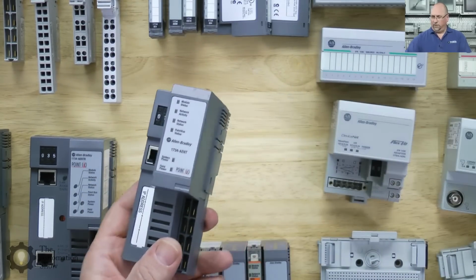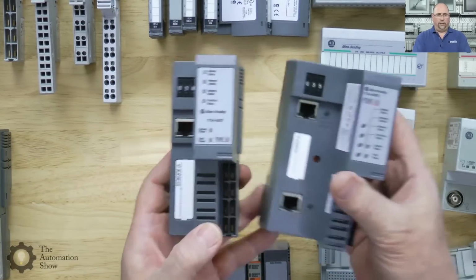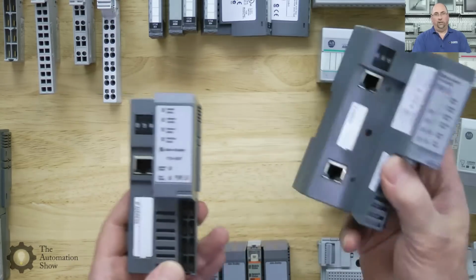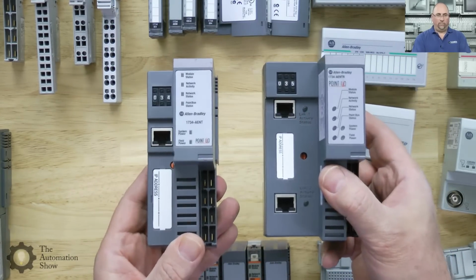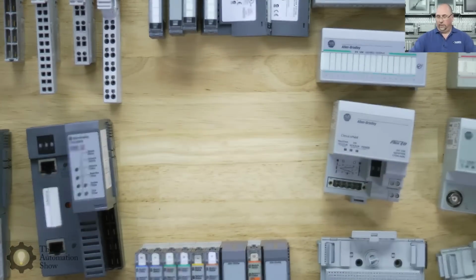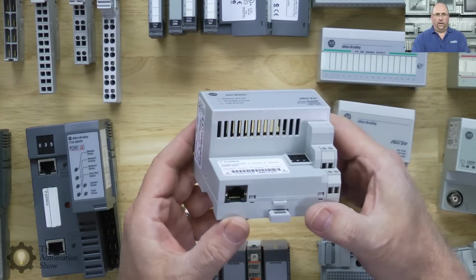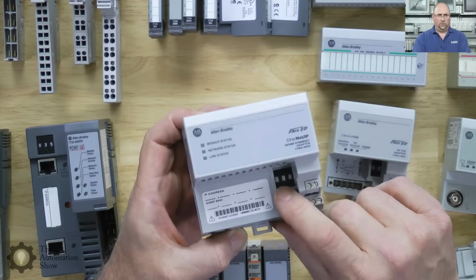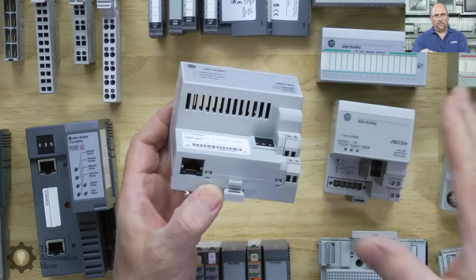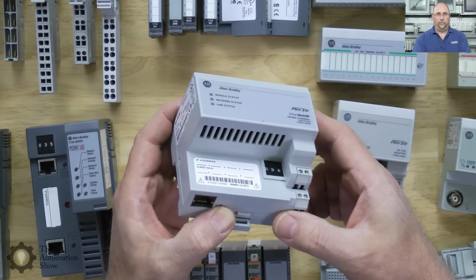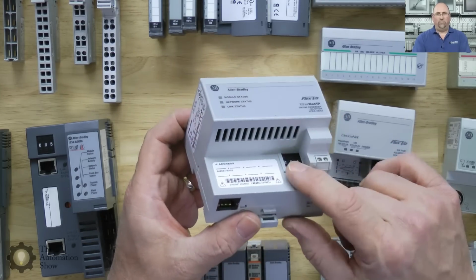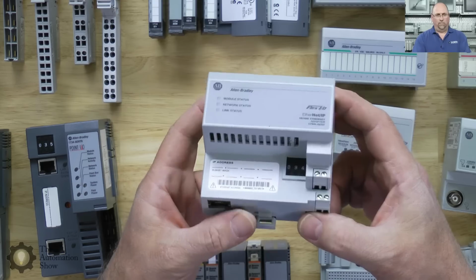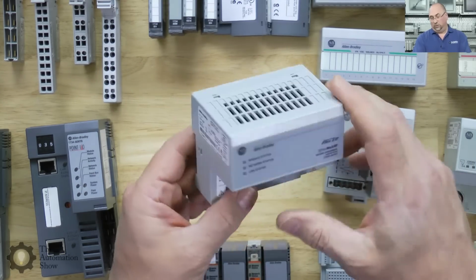Okay. Now, a couple of notices here. I've got two Ethernet adapters. This is a single port. This is a dual port. So this supports DLR and linear daisy chain connections. It's a big difference between those two. And this is the newer Ethernet adapter for Flex-IO. I have an older one on the wall. It doesn't have the thumb wheel switches for the node address, for the last octet of the default subnet. And those you really need to use BootP to set up. The BootP utility to set their IP addresses. But the newer ones do have that, which is a great addition.